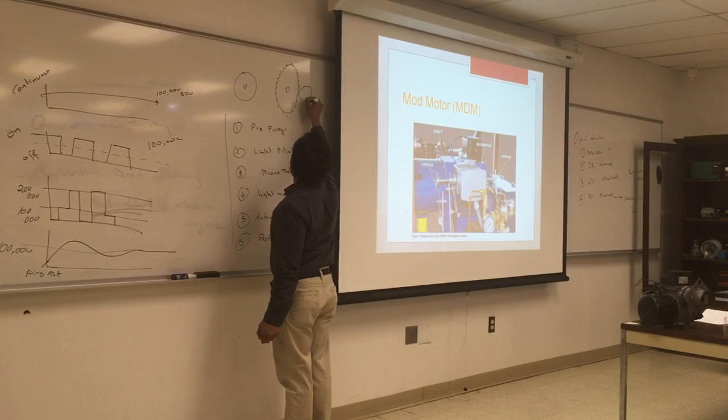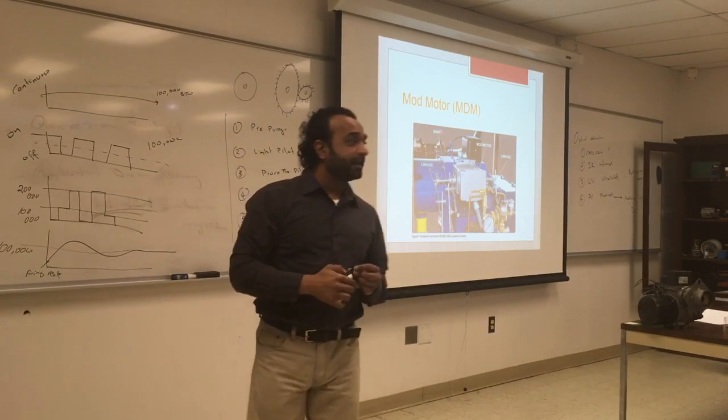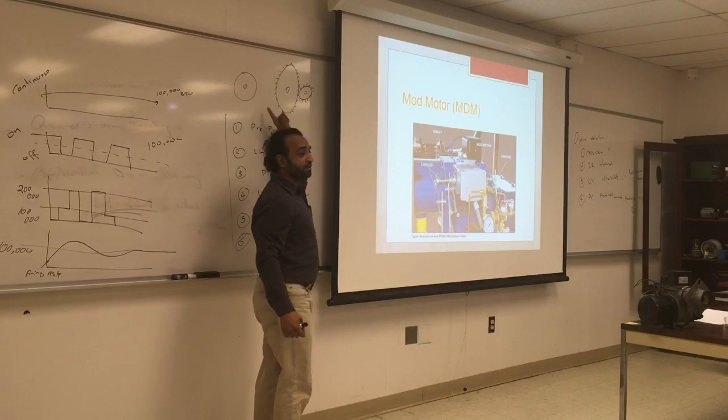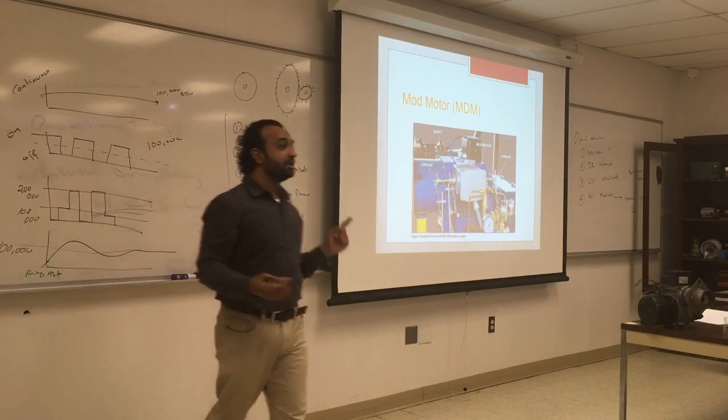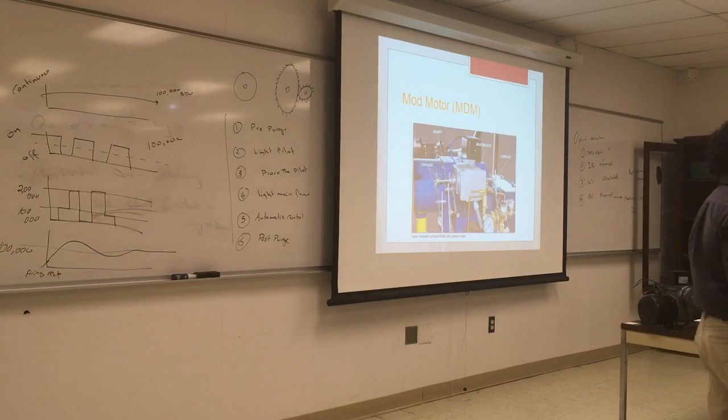So the main point of having a camshaft is you turn it, and when I'm close to it you turn and push, then when it steps away, it's not pushing. And this is how your car modulates between inlet and outlet. You have a cylinder, as it goes up, two valves open to bring in the fuel and air mixture. As it goes out, it closes those two and opens the other two. So it's a timing gear.